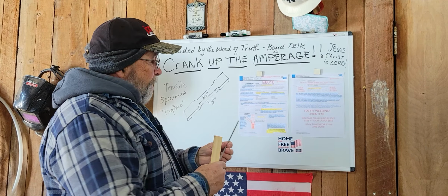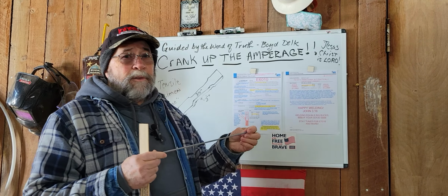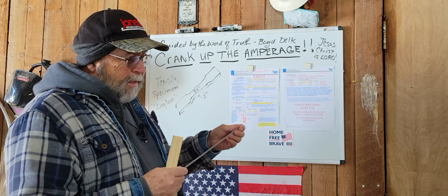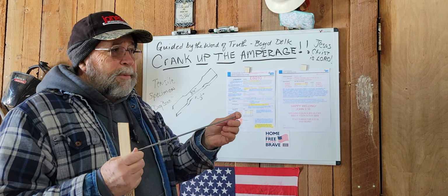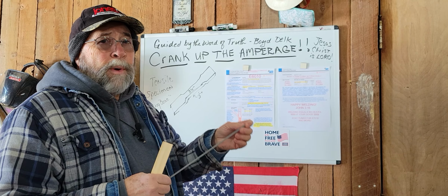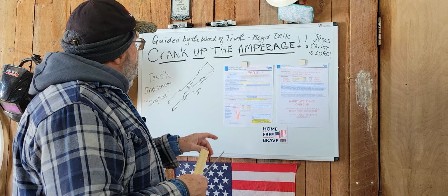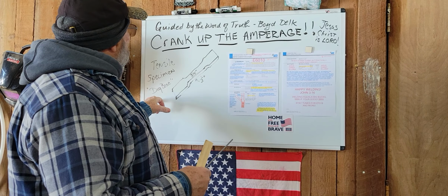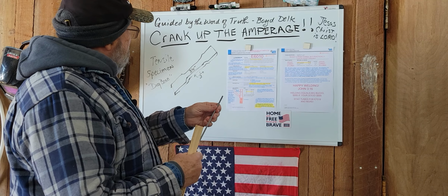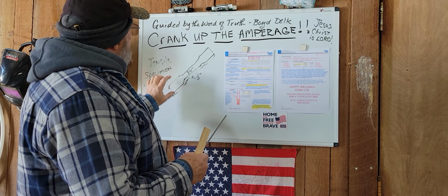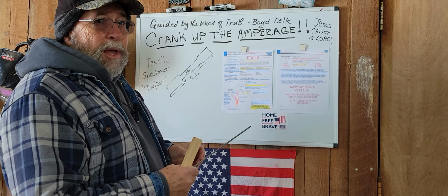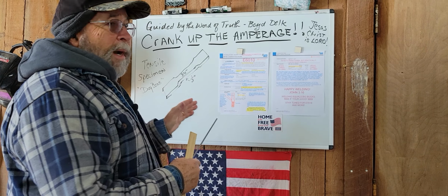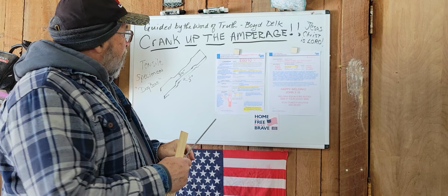So the tensile strength of this rod is 60,000 pounds per square inch, PSI. What that means is basically that the weld metal in this rod has been tested to fracture or break at 60,000 pounds. The way they test that is they cut out a dog bone out of this material, and you can see they clamp here in a hydraulic machine, and they pull until this metal breaks. Where it breaks is how they test the tensile strength.